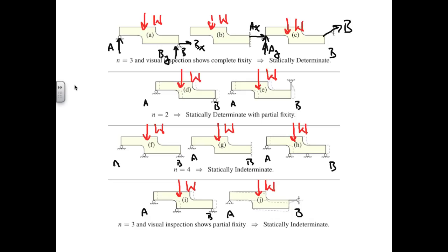If for some reason the force loading the body comes from below, this force induces a compression at B. But if the support is a cable, it can't support compression and the cable goes slack. Now the number of reaction components is reduced by 1 to just the two force components at A, and we can imagine the structure experiencing a rigid body rotation counterclockwise about A.